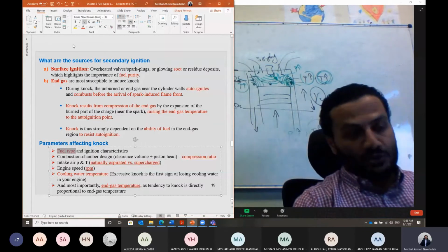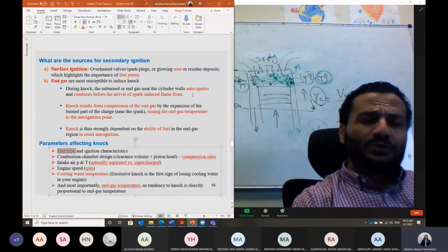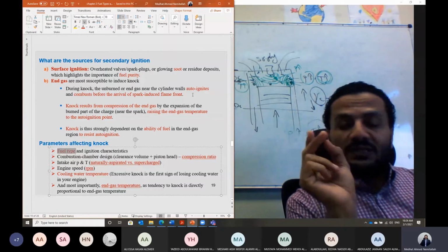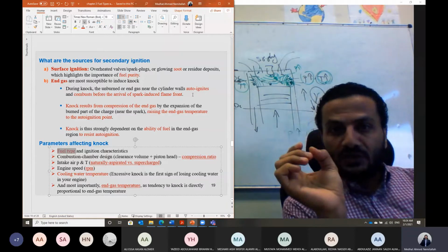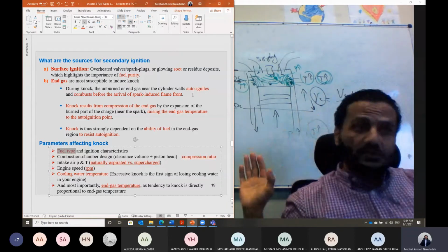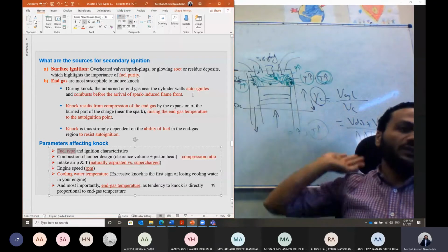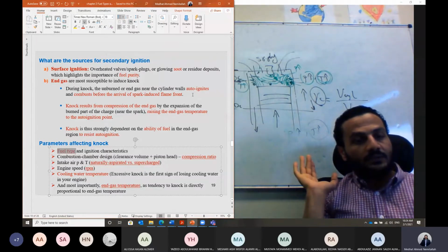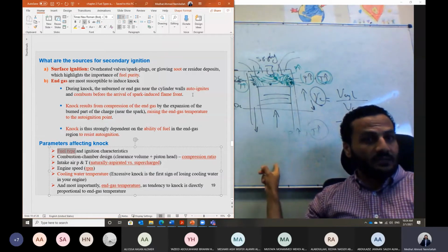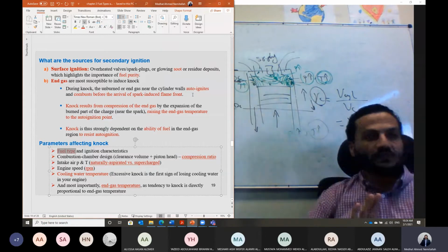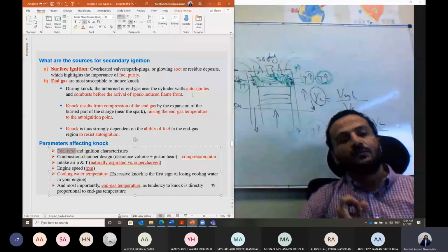And that's why in a gasoline engine we cannot design the engine to have a higher compression ratio. But usually, guys, don't mix it up. Usually the manufacturer of any gasoline engine designs the engine at a given compression ratio that will not result in engine knock. So the engine is designed at a compression ratio that will not cause self-ignition of the fuel.